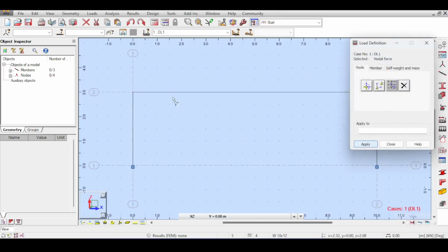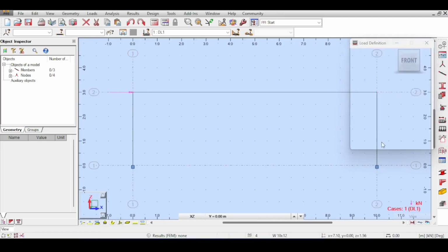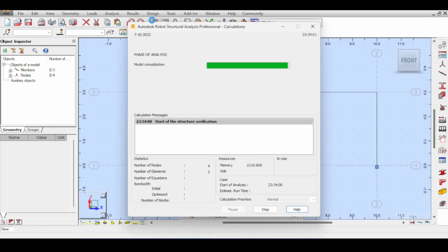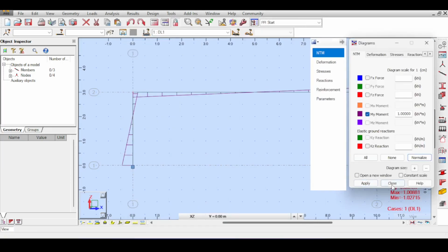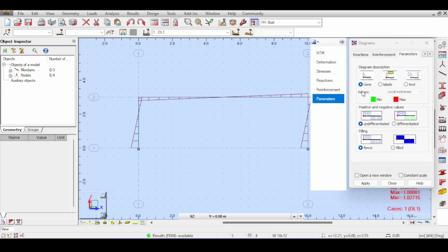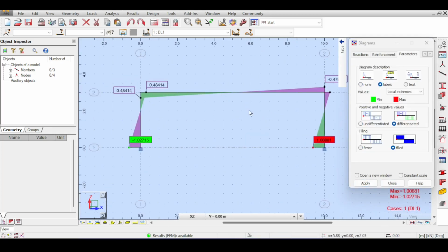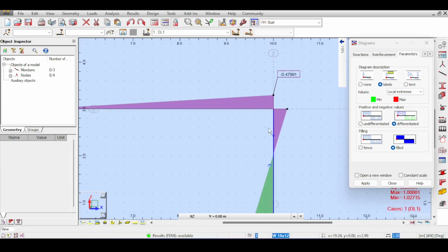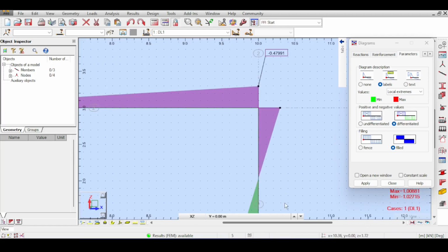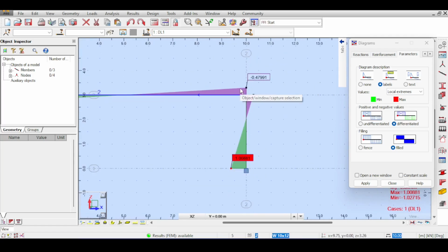If I add a 1 kilonewton force on this node, you will see that you have the typical moment diagram that is basically loading the columns, and of course the beam would have a linear moment diagram too. You can see this like this. Well, this is perfectly fine and is what we are expecting to see. Of course, if I keep increasing the forces, then the moments on those joints will increase. And at one certain force, the joint will be loaded so much that the cross section at that joint due to moment will yield and actually will fully plasticize.